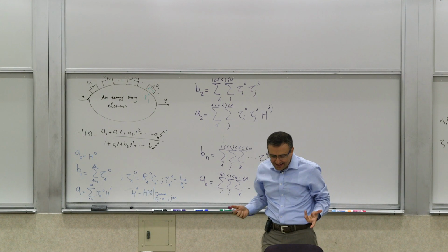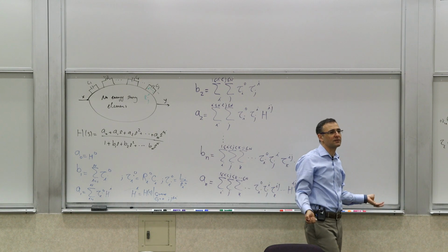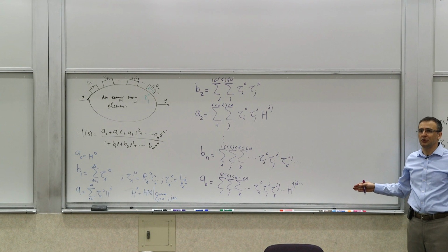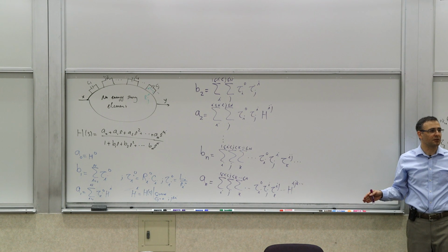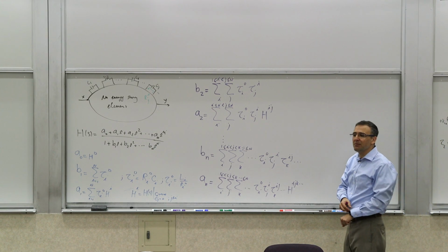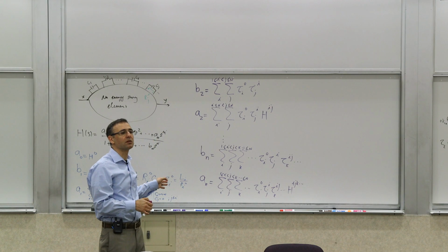Okay, so that is the big result. That is everything. This is called generalized time and transfer constants. So you can calculate all the coefficients. You don't need to write a single high frequency KCL or KVL, and you can calculate it to the degree you want. Now, the thing to remember is that you can calculate exact transfer functions using this, and I'll show you a couple of examples of that.